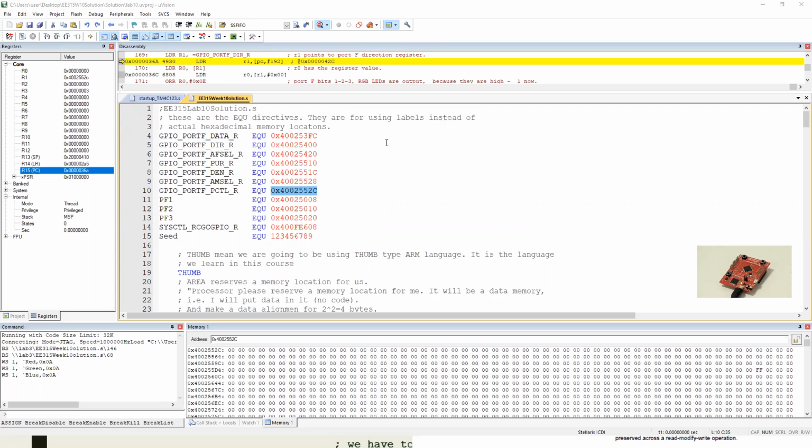Okay, so what I'm trying to say is, let's go over this, guys. This is important. This control register is mapped to this address. Each address occupies 8 bits. So that address is this guy, right? If you look at the data sheet, it will show you a long data sheet, right? So 32 bits. I'm going to write them in nibbles. So the first nibble, the second nibble, and so on. So I'll have 8 nibbles. 1, 2, 3, 4, 5, 6.